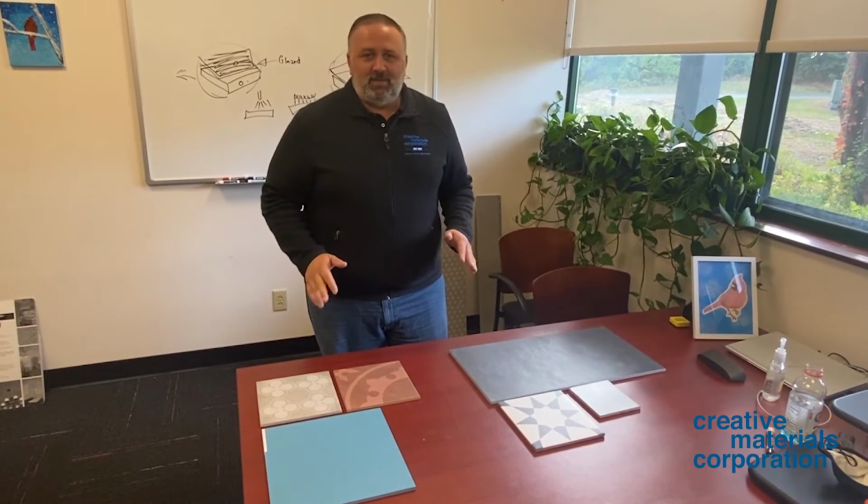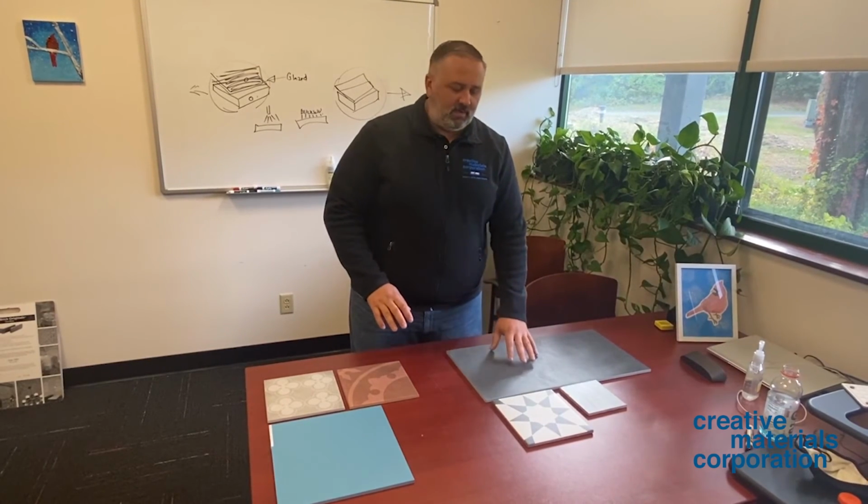So the takeaway from this discussion is when to use these products and where. Glazed tile, again, for 90% of the projects you're working on is suitable for use, even if it's a color body, non-color body. If it's a restaurant, if it's a multifamily, convenience stores, pretty typical usage for that material. When you're looking for a more durable product for floors or walls, get out of the habit of saying through body and into the habit of saying unglazed, because it opens up the aesthetic capabilities of these products to allow you to design more with better, more interesting looks.